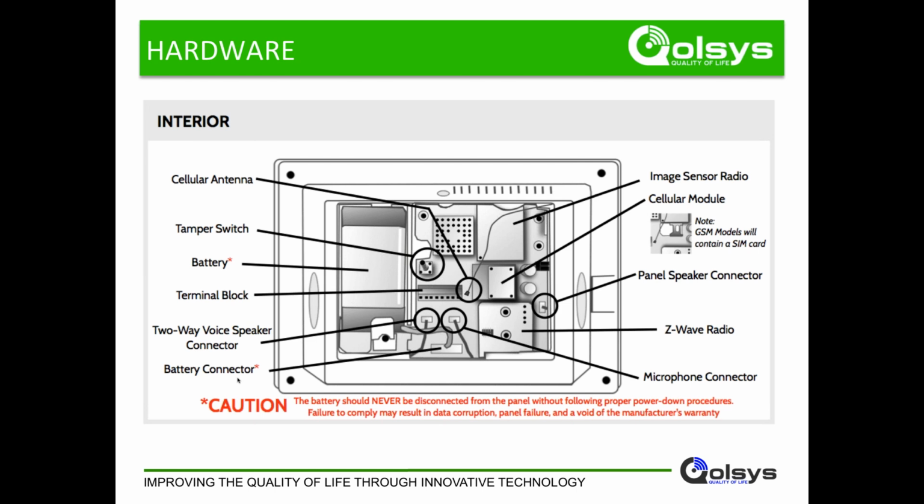And we think about this because this device is running an actual operating system, because it's a lot more like a computer. If you just unplug the power and unplug the battery, that would be like doing that on your laptop or on your phone. And we've all learned that on laptops and phones and tablets and things like that, before you open up the back of your laptop and crack it open and take the battery out, or before you unplug everything, you want to go ahead and shut down the software. And so same thing on this panel.